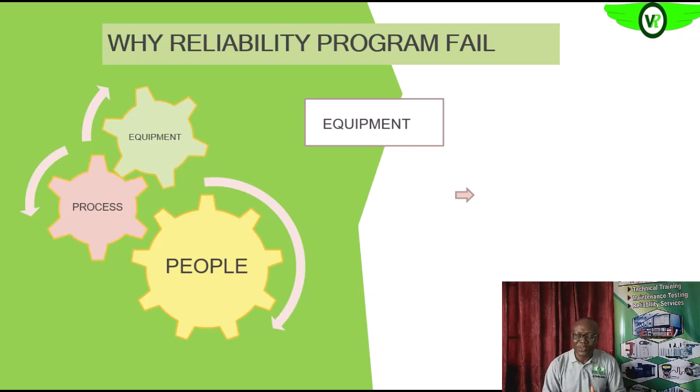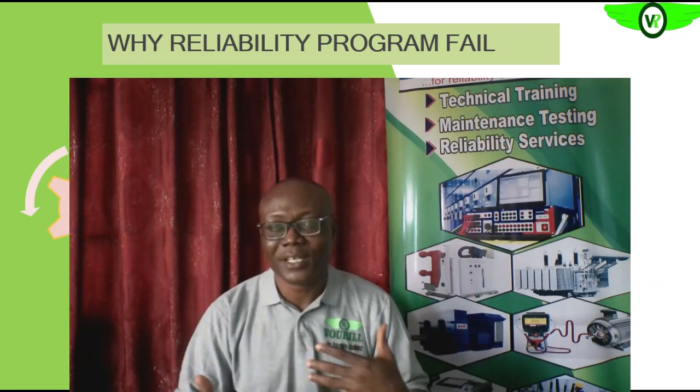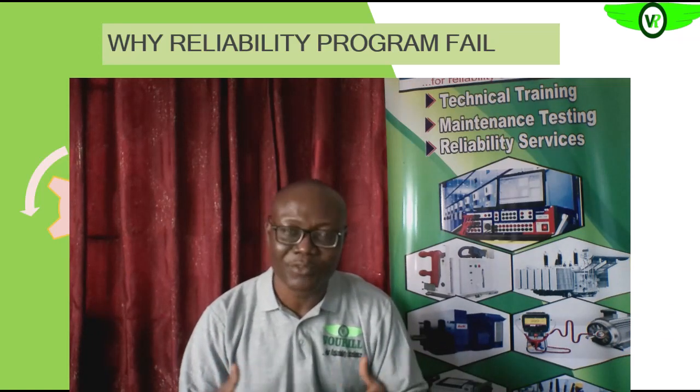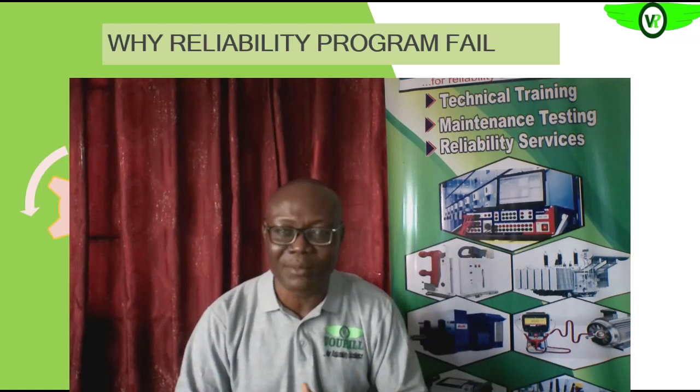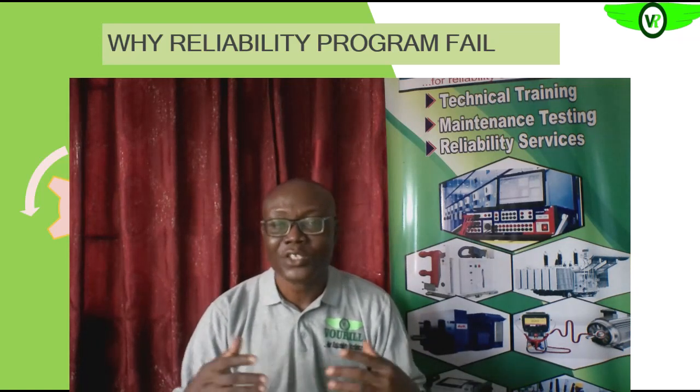Or we may say, okay, the equipment is failing so frequently, we assume, or maybe we carried out root cause analysis and discover that the problem is from misalignment of both couplings. We decide to deploy laser alignment technology during installation, after maintenance, and what have you.